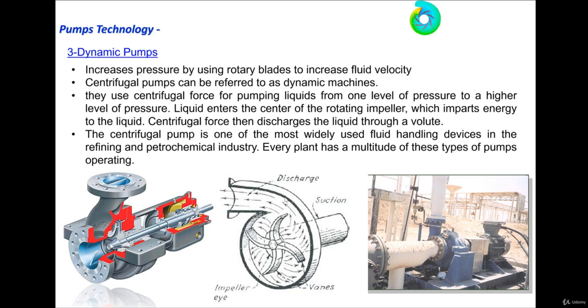The diffuser or volute shape is the part of the cross section of the pump that decelerates the flow. It is just a static part, whose purpose is to decelerate the flow and convert the kinetic energy into pressure energy. Due to the Bernoulli equation, as you know, total pressure is constant.